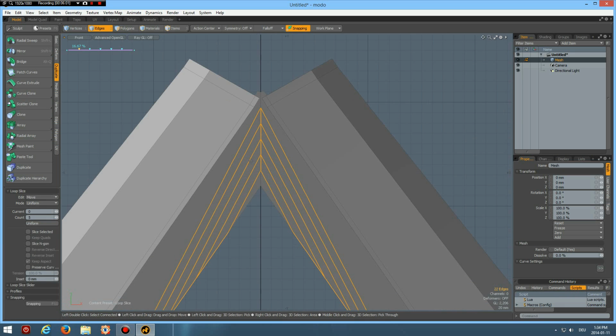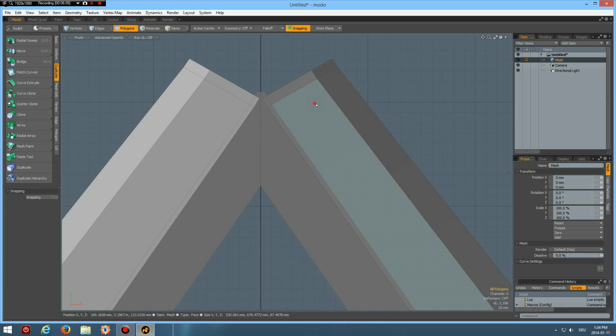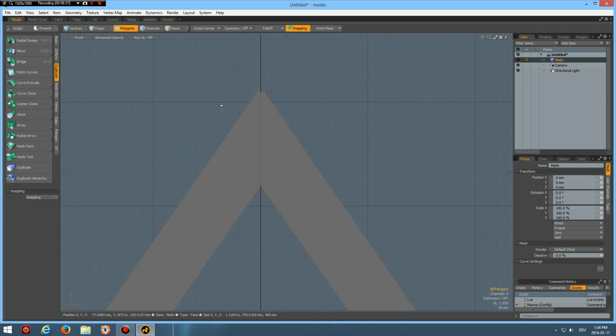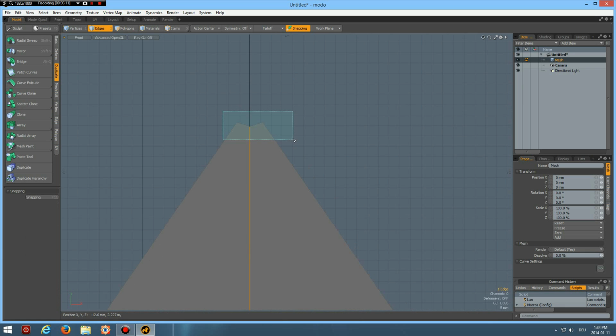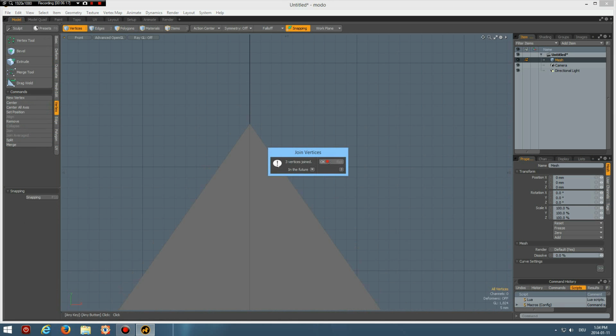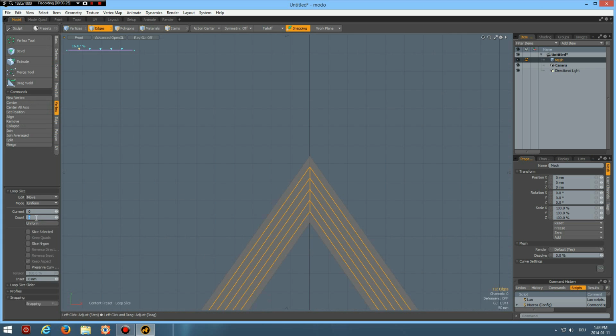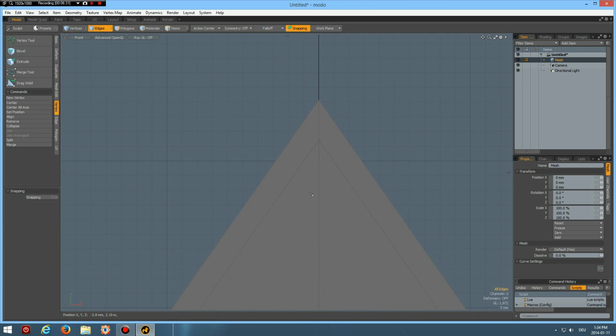We have a problem up here. Select these two and hide them. Our problem is this here. So select these three vertices. Go to vertex, join averaged. 3 vertices have joined. Let's see again. Alt C. Count of 2 and symmetry. Good.